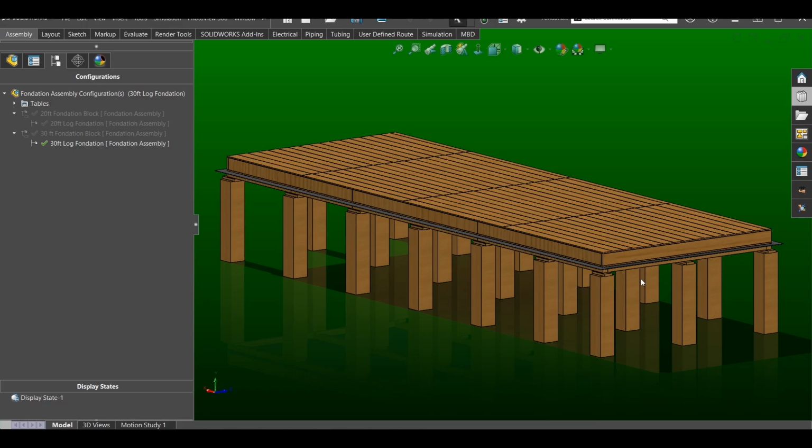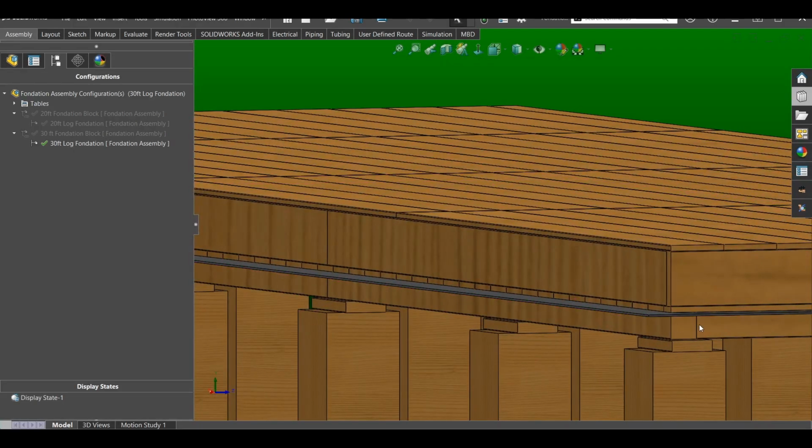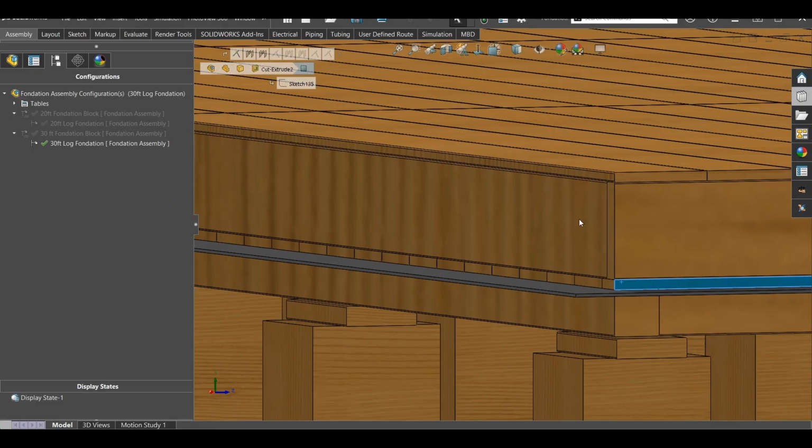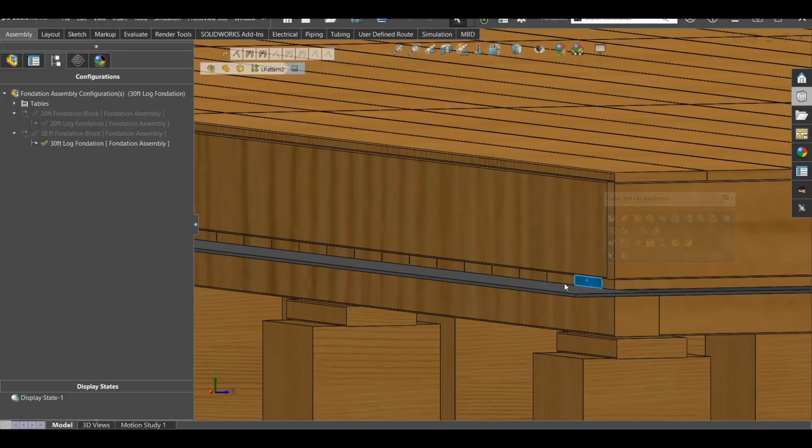Now we did look at the roof, and now we're looking at the foundation here. Like I said, it could move, and it's simple, right? It's 4x4 with 3/4 inch, 2x8, 3/4 inch for the subfloor. And this, I think, is optional, maybe, I don't know.